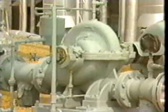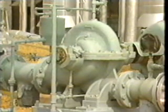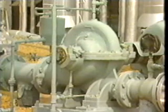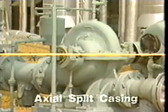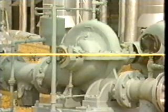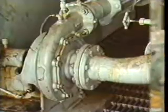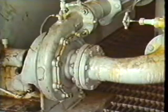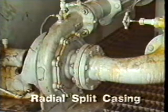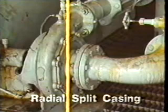Split construction pump casings are either axial or radial. They're axial if the split is along the center line of the shaft. If it is, the upper half of the casing can be removed, giving easy access to the pump shaft, impeller, and bearings. Radial splits are perpendicular to the center line of the shaft. The advantage of this design is that the casing can be made up in segments and bolted together to form one pump.